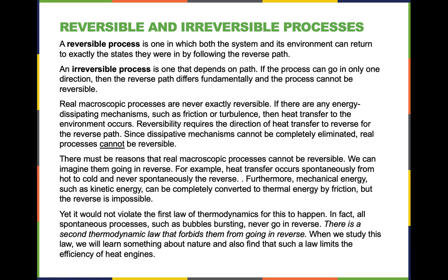If there are any energy dissipating mechanisms such as friction or turbulence, then heat transfer to the environment occurs. Reversibility requires a direction of heat transfer to reverse for the reverse path. Since dissipative mechanisms cannot be completely eliminated, real processes cannot be reversible.